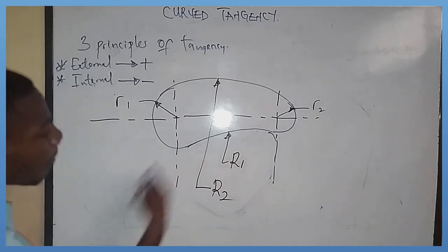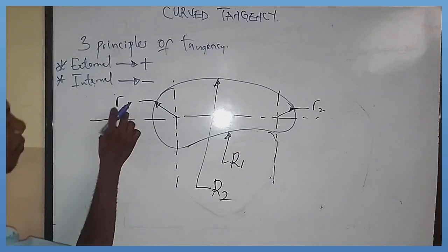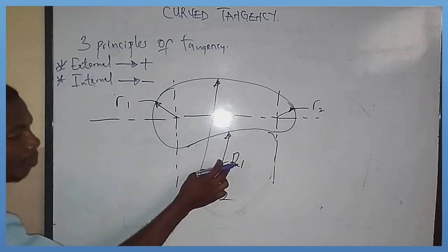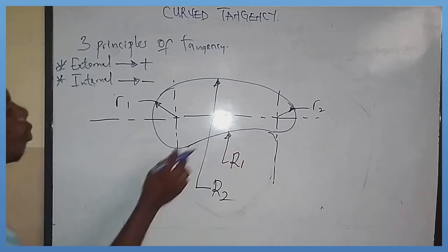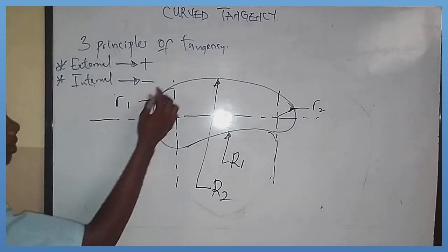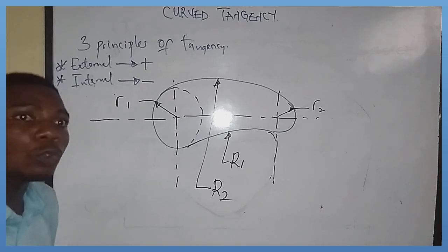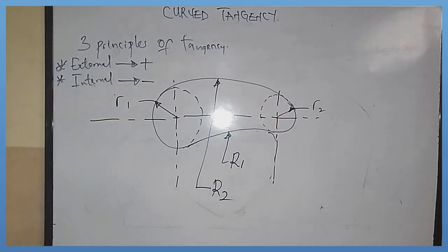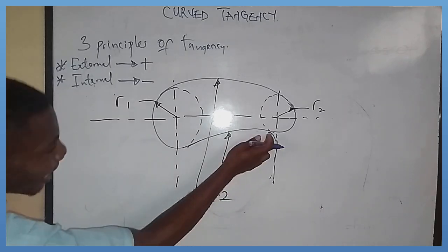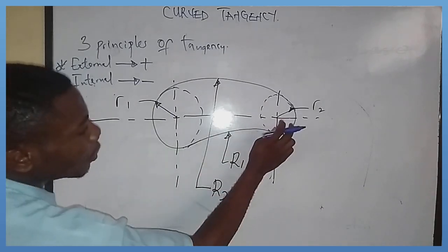For this bottom part where we are applying addition, the arc of radius big R1 touches the arc of small r1. Big R1, that's the dimension for this arc that goes here. The area you are looking at is actually a complete circle, but they won't show you that it's a complete circle, so you need to deduce that also, alright? This area is also a complete circle. So back to my explanation. This arc at the bottom here is big R1, this circle here is small r1, and this smaller circle here is small r2.